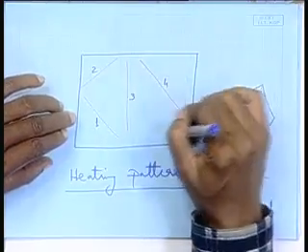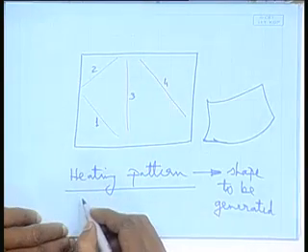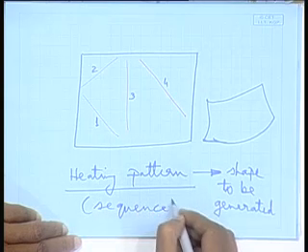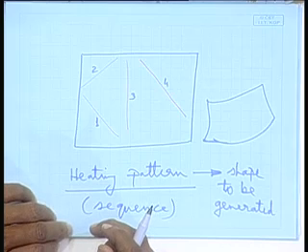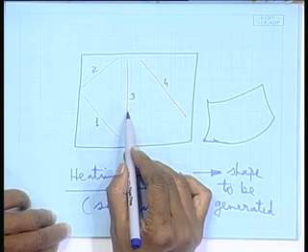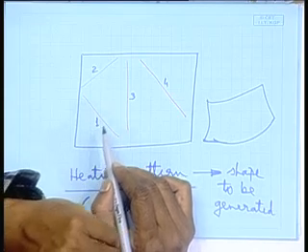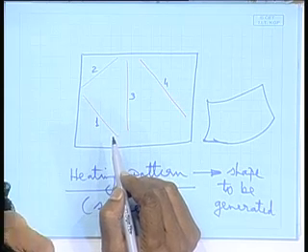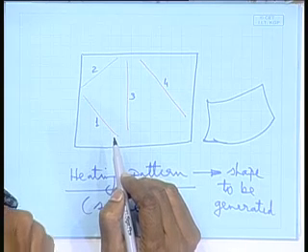It is not only important to know the heating pattern, but the heating pattern also involves the sequence of heating: not only the magnitude of heating and speed of heating, but also the sequence. Whether I first heat at position 3 or first at position 1, all these are to be worked out. So, if accidentally more bending was done, then, yeah, reverse. Right.